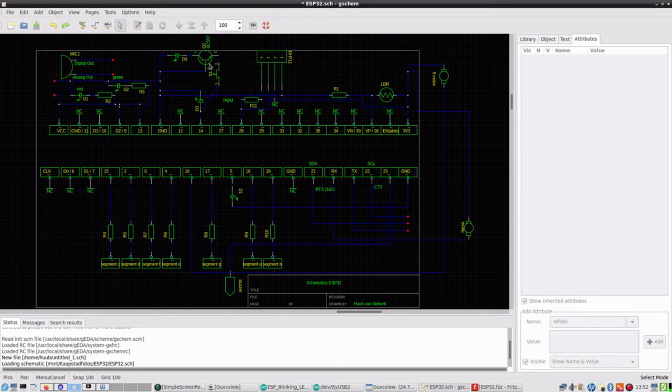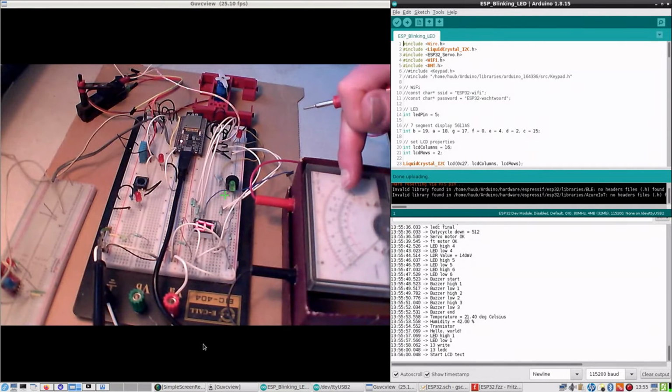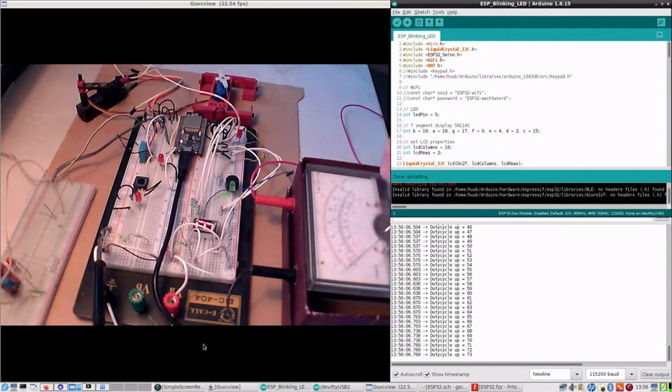Checking the voltages is a correct way to do it as well, and I have a multimeter at hand. So let me try that. Save the change in here, then plug in the multimeter. So multimeter in place, set to the full scale of 30 volts, which means that 5 volts and lower is really in this range.